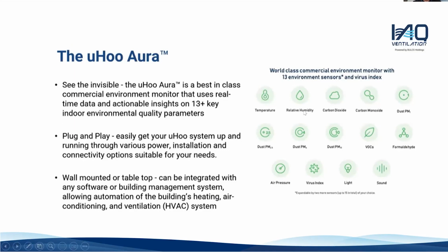So the system measures temperature, humidity, carbon dioxide and carbon monoxide. The dust particulates we talked about are PM2.5, PM1, PM4 and PM10, in microns. It also measures VOC, formaldehyde and air pressure, and there is a virus index, which is something YuHu has developed.